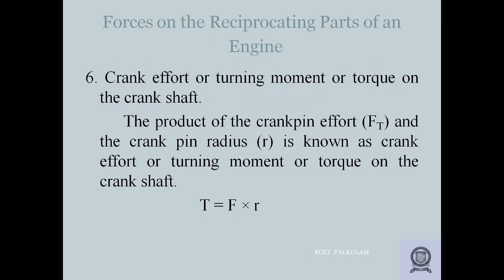Next is the crank effort, or the turning moment, or torque on the crankshaft. The product of the crank pin effort and the crank pin radius is known as crank effort or the turning moment or torque on the crankshaft. T is equal to F into R.